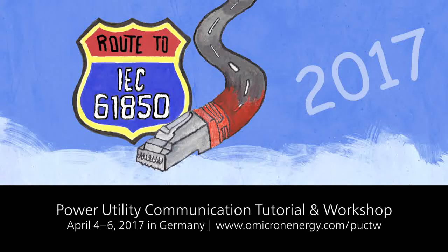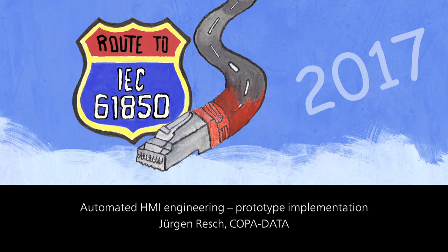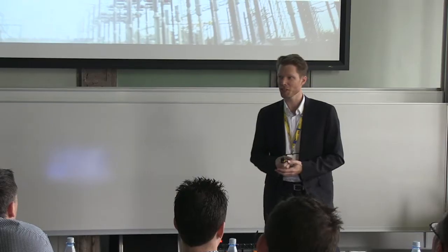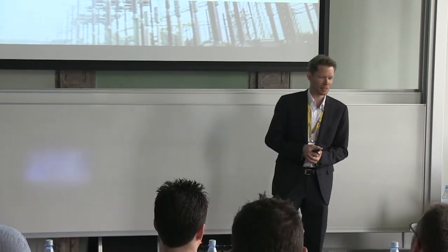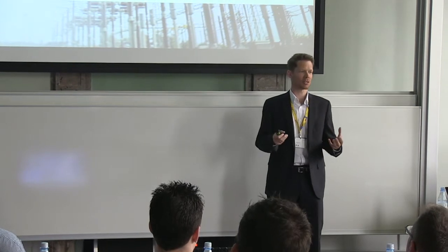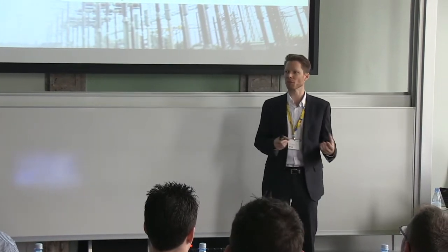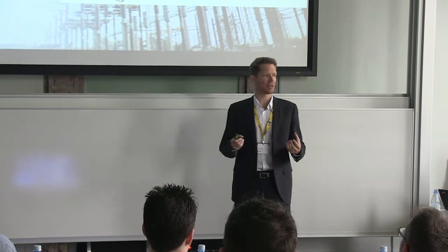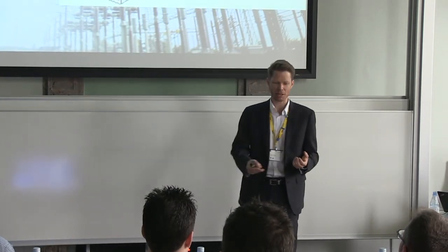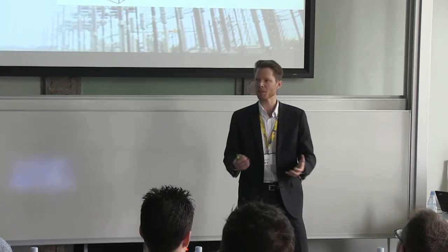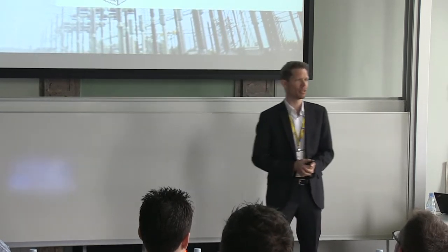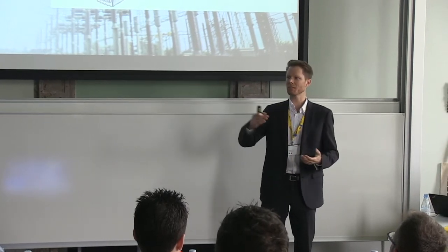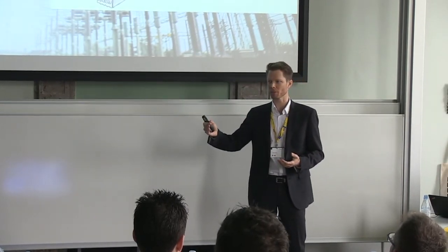Okay, today we heard a lot about switches, infrastructure actually. We heard about time synchronization, also kind of infrastructure if you want. Why I'm saying infrastructure? Because from an HMI vendor point of view, it is a given thing. It's like a power plug in the wall where the power always comes out. So it's also given that there is power. For us, as an HMI vendor, our horizon ends at the TCP implementation of Microsoft Windows.